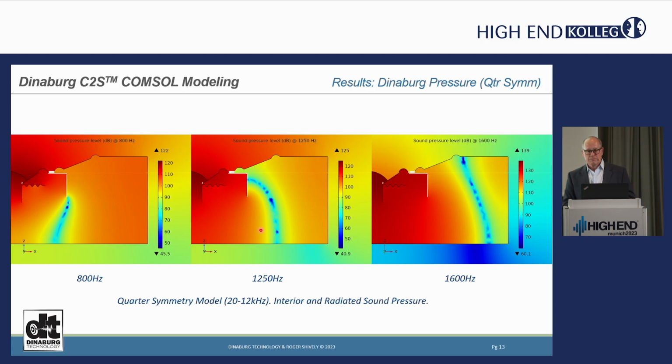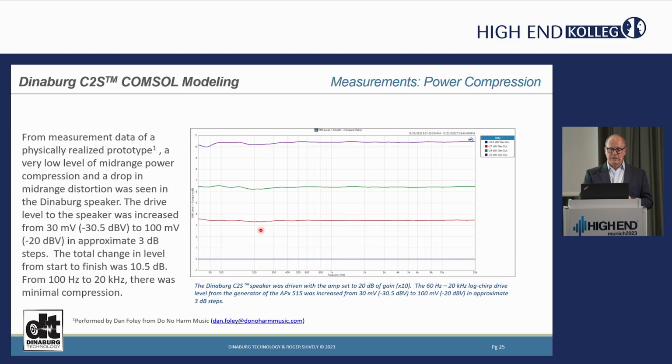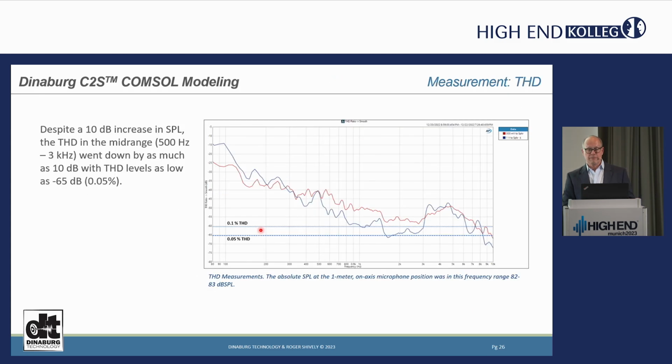Yeah. And the other aspect I didn't talk about, which was somewhat related to the measurements that were done, is that with the passive radiator, they were obviously helping the 3-inch. Now the 3-inch can take, with the THD measurements that we saw, a higher power input and still not have the distortion that you would typically associate with that in a 3-inch diameter loudspeaker. It's capable of producing more low frequencies without having to be as much excursion, and so it stayed linear for a greater power level.